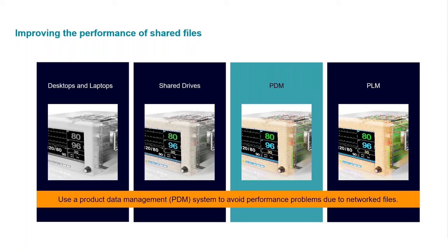So this gives you the advantage of working on shared files without the normal disadvantages of sharing files across the network. PDM also helps you avoid complicated rules aimed at avoiding overwriting other users' changes, revision control on solid models, and tons of additional file management problems. So if you're concerned about your assembly performance, a simple PDM tool should be a priority.